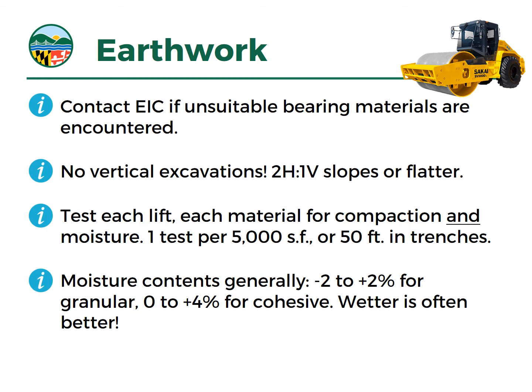And vertical excavations tend to create what is called arching effects, where you get poor compaction and then lower stresses, and again, that differential settlement or cracking.